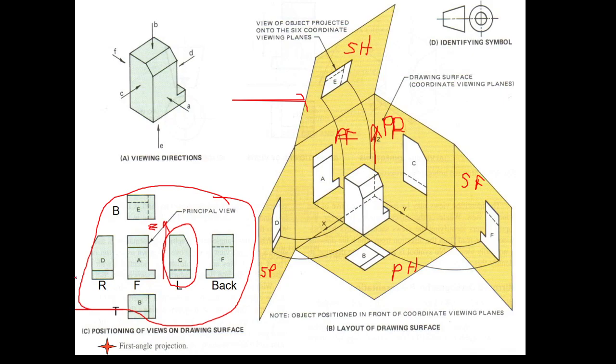If the drafter, at the view construction stage, constructed the images at their correct places, correct in shape and correct in size, using the coordinate axes: between the front and the top, we have the x-axis; between the front and the left, we have the z-axis; between the top and the left, we have the y-axis. Although in space the y-axis is unique, here it is along the folding line between the primary profile and primary horizontal picture planes.